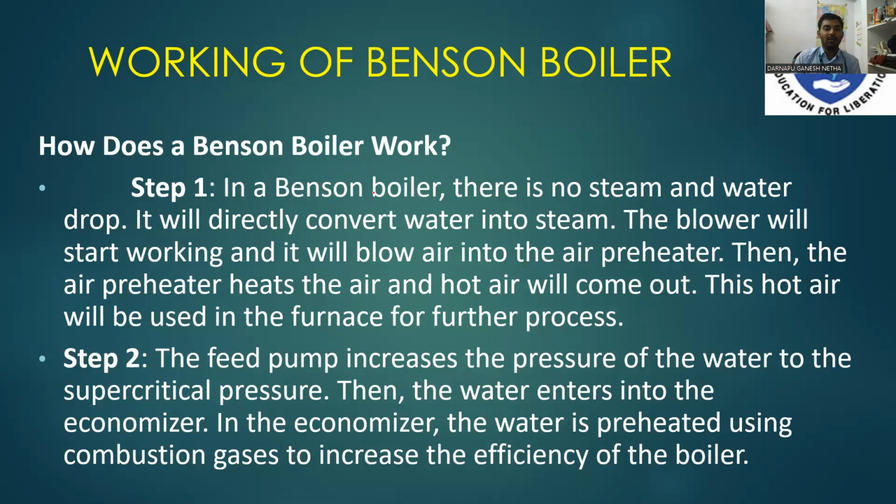How does the Benson boiler work? Step one. In the Benson boiler, there is no separate steam and water. The water is directly converted into steam. This point tells us that because there is no separate steam and water, there is no requirement of a drum. So the Benson boiler is known as a drumless boiler.